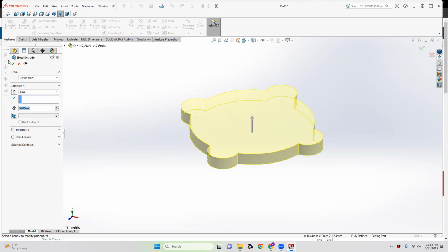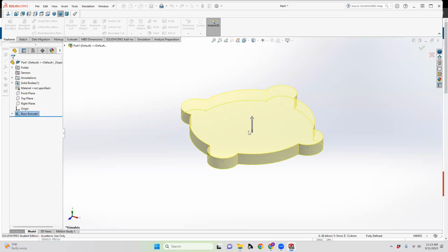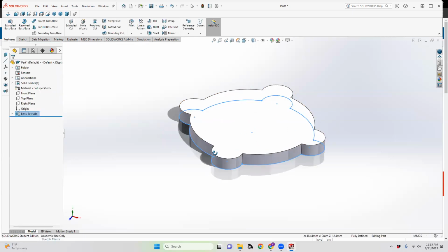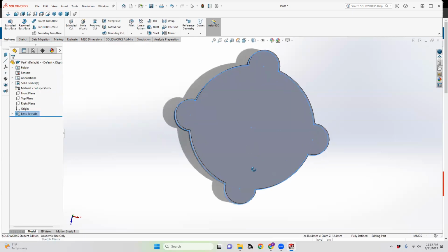What we're trying to do is perform an operation. We're trying to perform a feature, one of these operations, on a given sketch area. And so maybe this has two different areas that we want to control. So I'll show just a simple extrusion here. We hit the check mark. I already know it's a fully defined sketch.